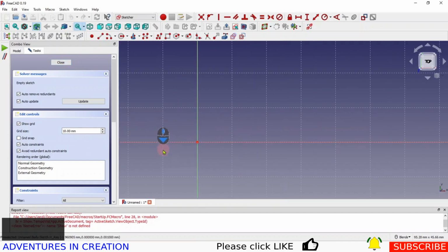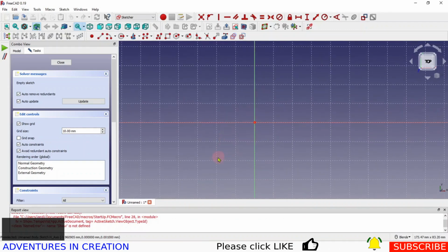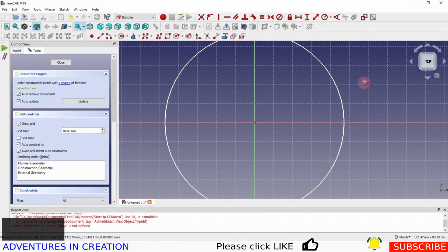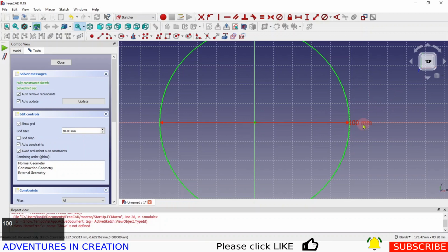So what we're going to do, this coaster is going to be very simple. It's going to be a circular coaster. So we're just going to pop it on center there. It's going to be 100 millimeters in diameter. One thing I want to point out, when I do these constraints, if I'm constraining a diameter, I use the diameter one rather than the radius. That way I do no mental math. So if I want it to be 100, I'm just going to say OK. And now my circle is 100 millimeters in diameter. I'm going to close that.